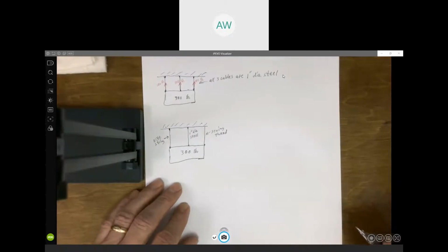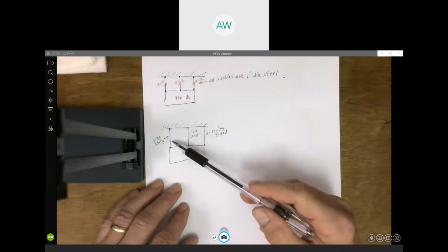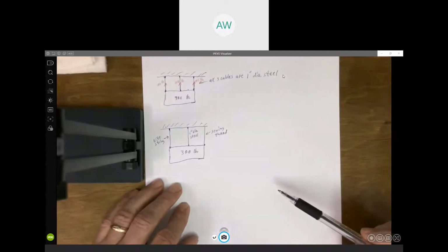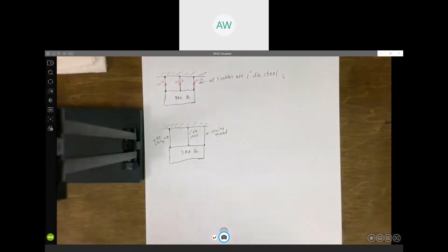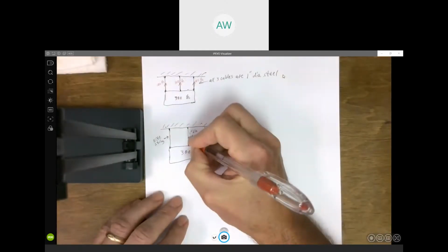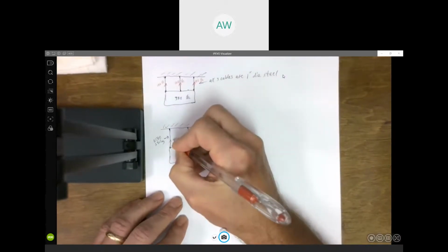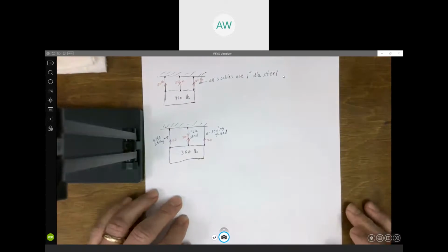Is the force still going to be the same in all 3 of those? Yes. The geometry is exactly the same, but I think most people would tell me there's no way this kite string is going to have 100 pounds in it. It'd break. Same thing for the sewing thread. So in this configuration, what you would find is pretty much all the 300 pounds is going to be carried by that steel cable, and almost nothing. The force in those two is going to essentially be 0.